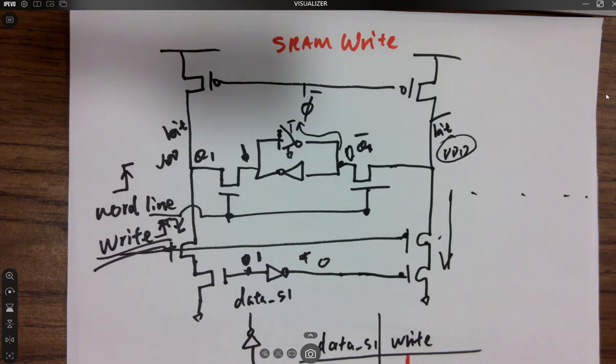Okay, you always want to have a balance between the size of the memory in your application and the cost. So if you're doing SD card writing and reading, you probably need a bigger RAM, because an SD card requires 512 bytes to be read and written at the same time. So you need a bigger memory for the buffer.